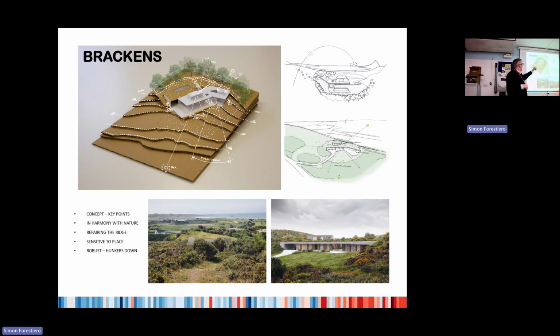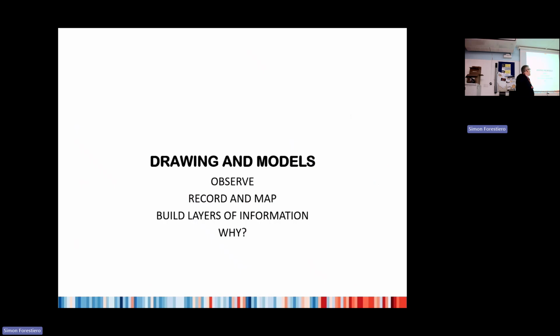But we've also got a courtyard at the back that allows the morning sun to come in. So we've really played with gaining every little bit, and that's what your schemes can be: just use the existing environment to generate what you do. So we keep summer sun out with the overhang, and we let winter sun in, so that the heating bills are much smaller.